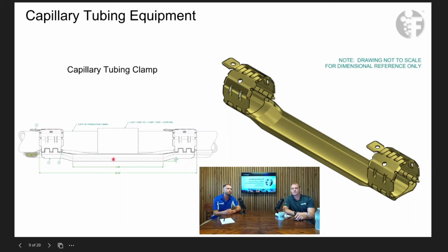Yep. Okay. Because what's the other way to attach your cap tubing besides a clamp? Well, that's bands, right? Okay. So, I mean, bands are good, but clamps are just way better, right? Because with the bands, they could either be erosionally broken or mechanically broken if they hit the casing. That is common, that does happen. That's the reason why we go with that 10-degree rule for clamps.